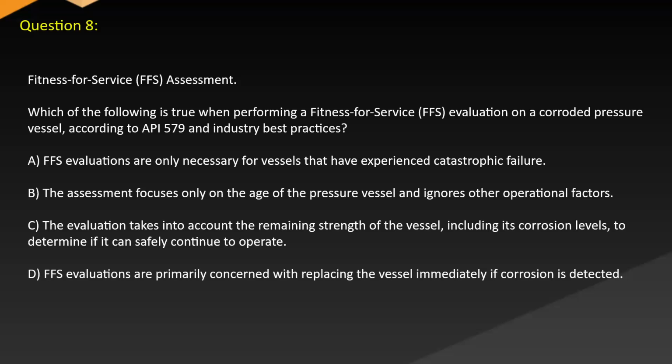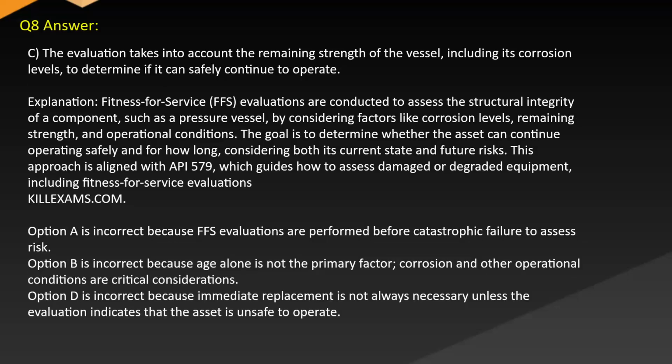D. FFS evaluations are primarily concerned with replacing the vessel immediately if corrosion is detected. Answer. C. The evaluation takes into account the remaining strength of the vessel, including its corrosion levels, to determine if it can safely continue to operate. Explanation. Fitness for service, FFS.